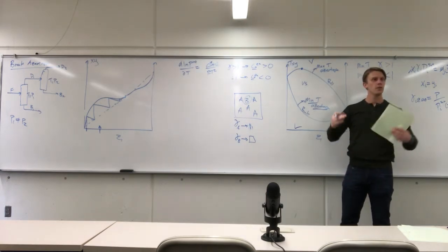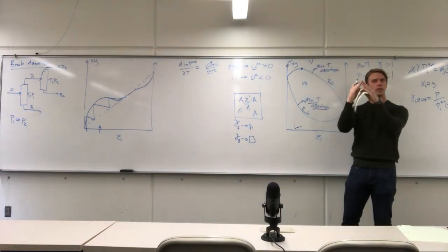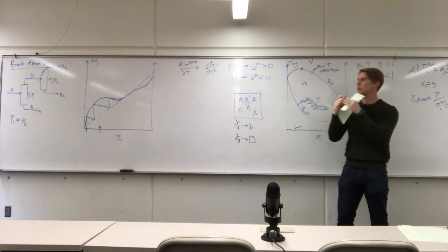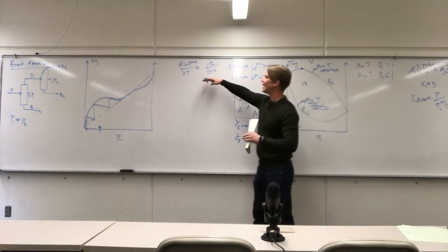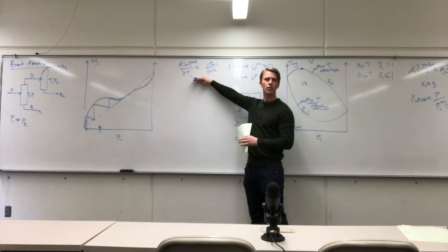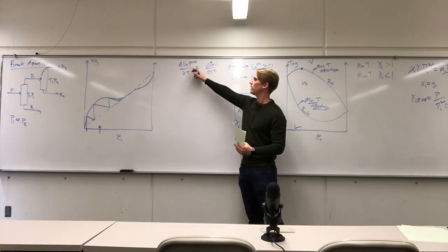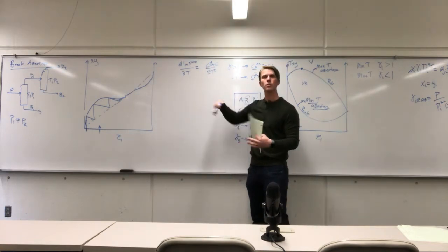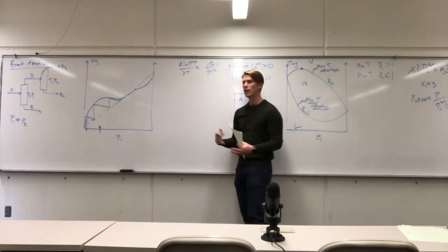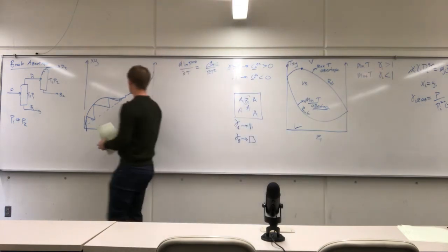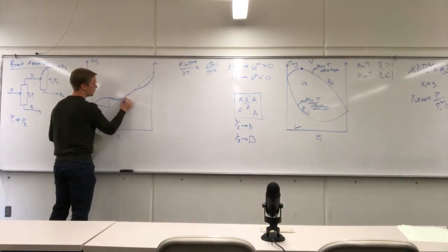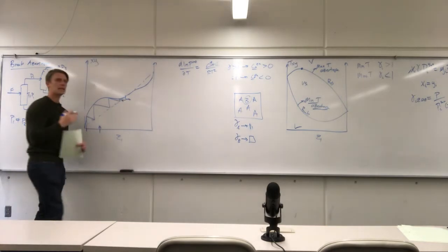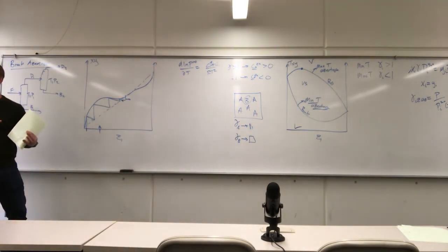So for any fluids, just because you hit this perfect little nexus of properties that you form an azeotrope, it's unlikely that that's going to persist for all temperature and pressure conditions. Right? The heat of vaporization is related to the vapor pressure, and the heat of vaporization is related to how close you are to the critical point and your cohesive energy. Changing the pressure is going to shift your azeotrope composition a little bit to the left or a little bit to the right.